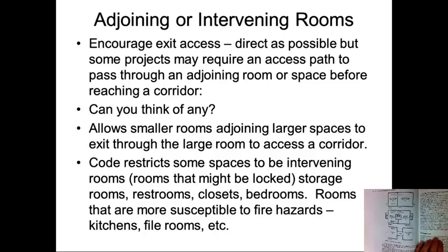It allows smaller rooms adjoining larger spaces to exit through the large room, and code restricts some spaces from being intervening rooms, rooms that may be locked. Sometimes you see on a restaurant building a sign that says these doors may not be locked anytime the business is open. Storage rooms, restrooms, closets, sometimes bedrooms, and rooms that are more susceptible to fire hazards, like kitchens and fire rooms, etc.